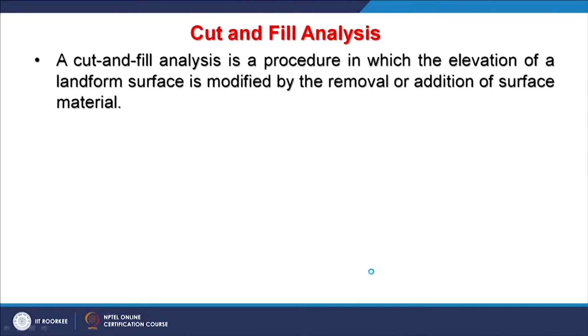procedure in which basically the elevation of a landform surface is modified by removal or addition of the surface material. So where this material has to be cut from, and where it will be filled, that can be decided based on this cut and fill analysis. And in this analysis, the areas and volumes of change are summarized.